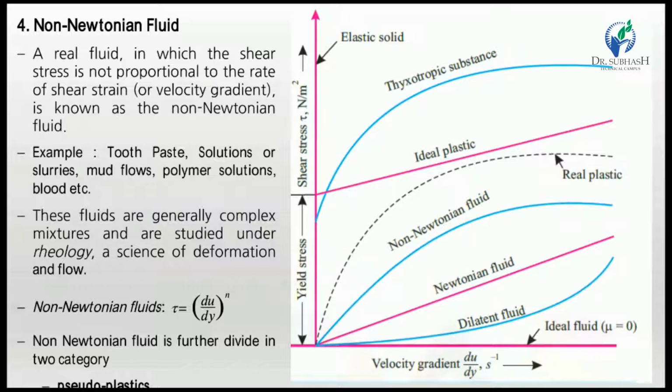Non-Newtonian fluids are generally complex mixtures and are studied under rheology, the science of deformation and flow. The non-Newtonian fluid equation is shear stress is equal to k times du by dy raised to n.